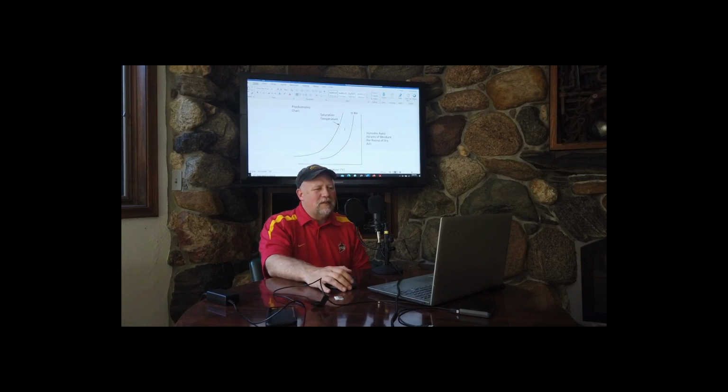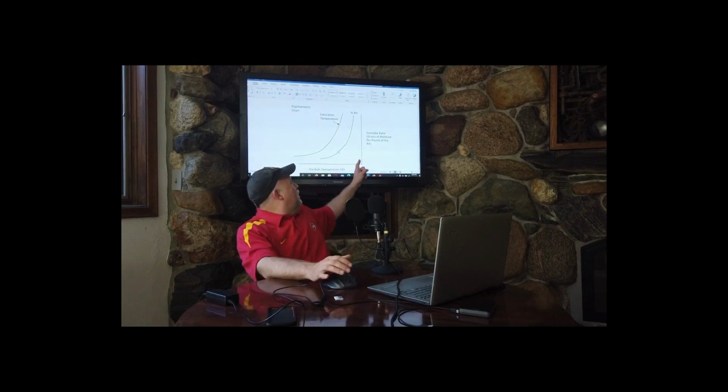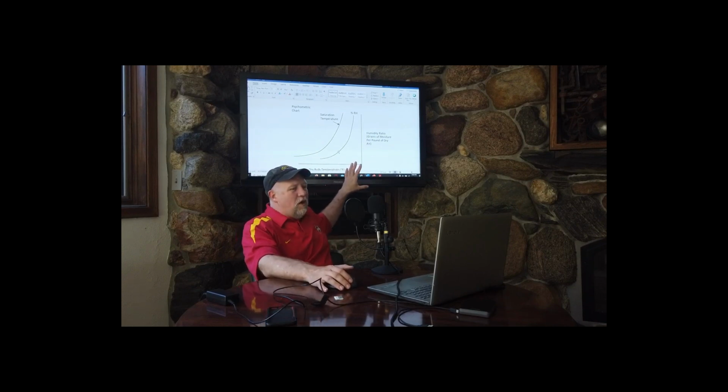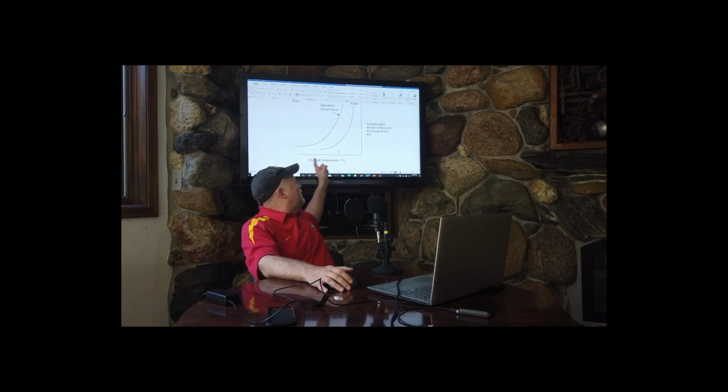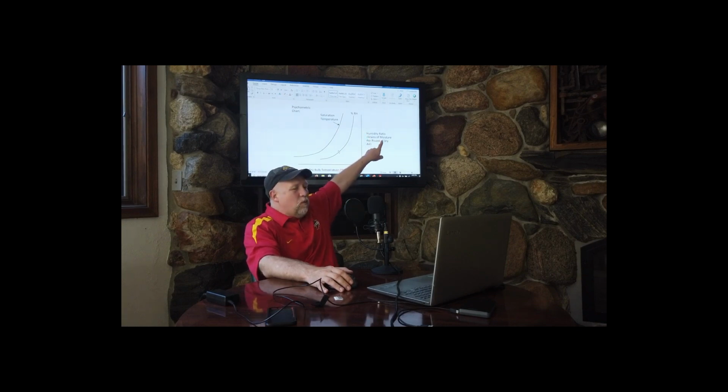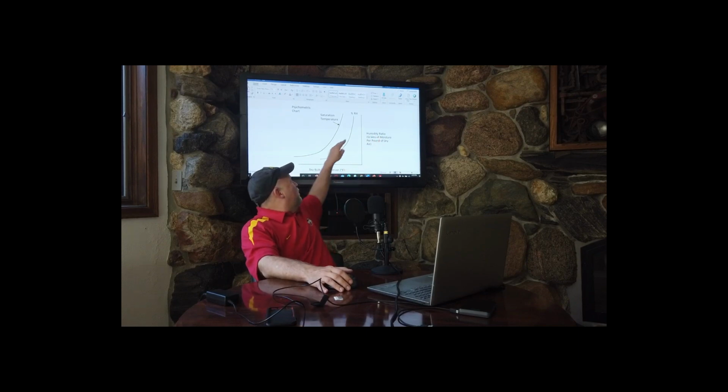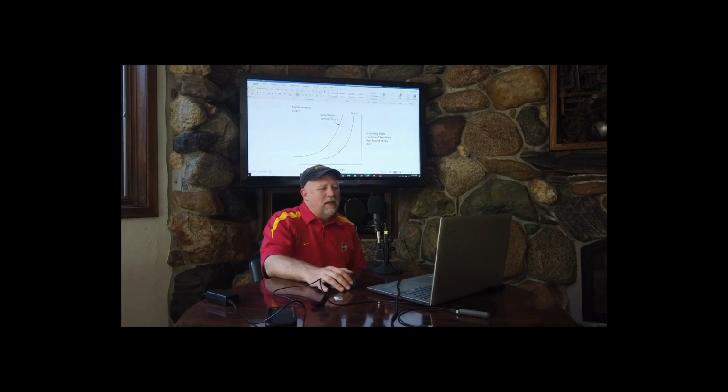All right, this is the chart that I had you download, this one. This is just the simplified version. Here is that curve, all right? This chart represents all the possible combinations of dry bulb temperature here on the bottom. The axis that goes on the bottom is dry bulb temperature. The axis on the right is humidity ratio, grains of moisture per pound of dry air. These curved lines are percent relative humidity.